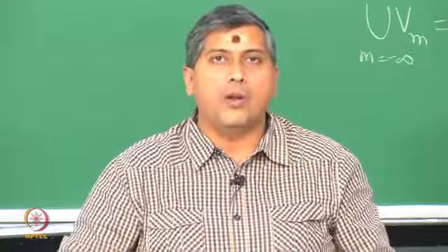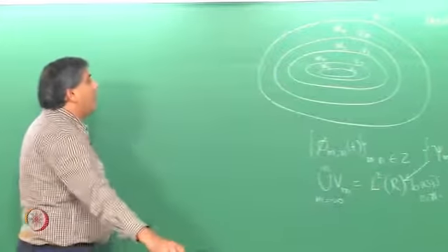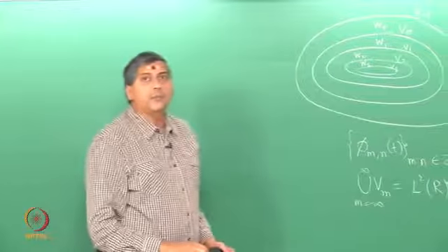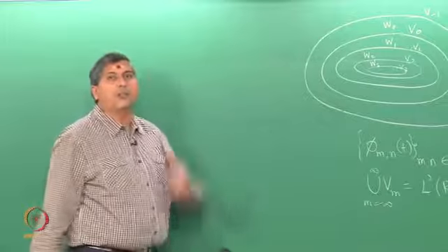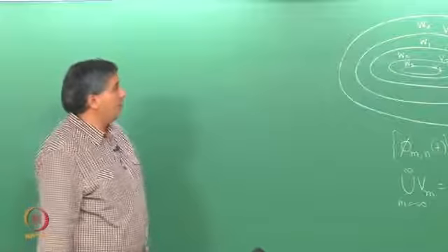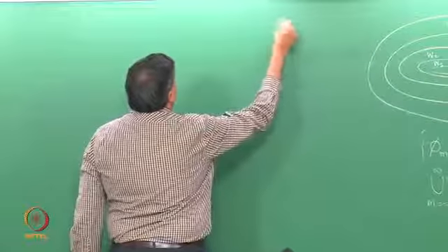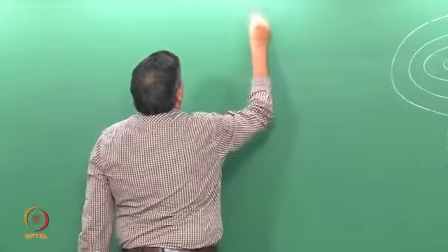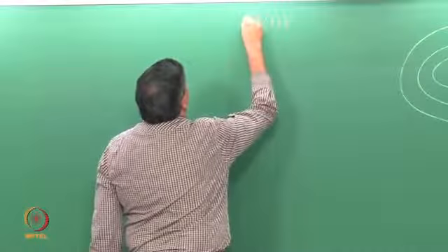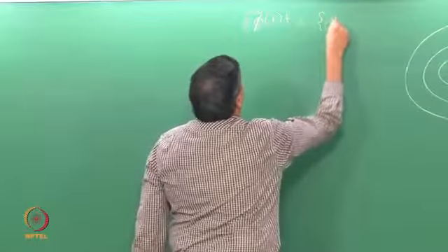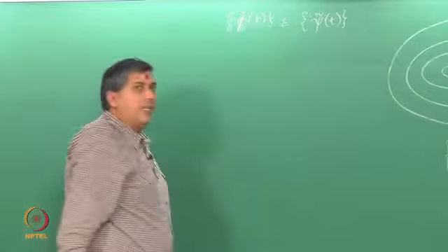All right. So, let me again show what I mean by that. Just as we have here approximation and detail spaces spanned by the scaling functions and wavelets, let us call them decomposition filters. I can also have spaces spanned by the synthesis scaling functions and synthesis wavelets. We have used this before, we have mentioned that in CWT as well.